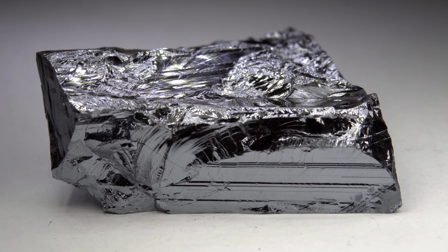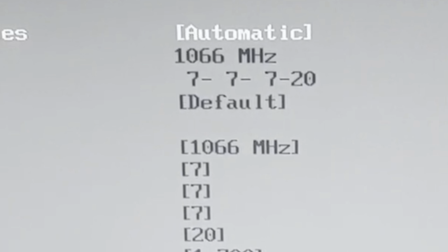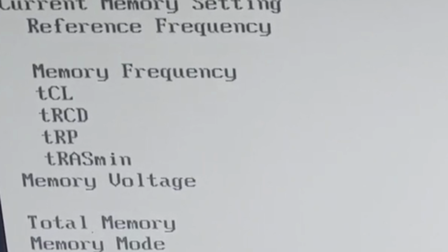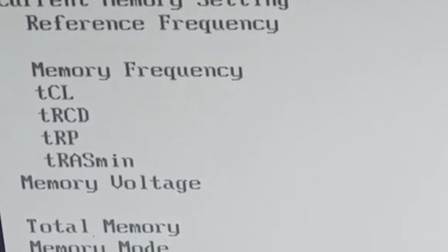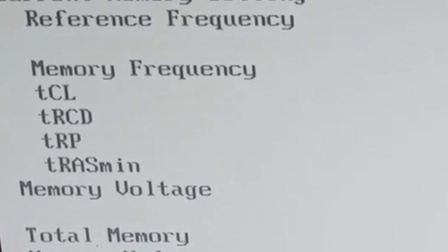When silicon heats up, its ability to conduct electricity increases. I would speculate that this would require that the RAM states would need to be refreshed more frequently when operating at higher temperatures. If this were the case, then I would expect that certain sets of RAM timings would operate perfectly normal when the computer is cool, but for those same RAM timings, when the computer gets closer to its maximum operating temperature, the refresh times may no longer be adequate.